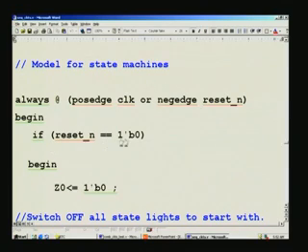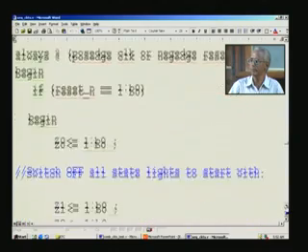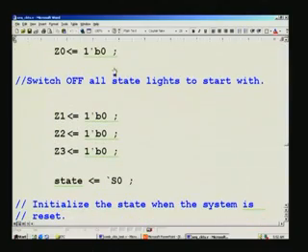So, once again, when reset is encountered, we clear all the outputs here in this case, and initialize to S0 state. Note that I have made it 0, you could have made even 1 as such, because that is what the starting state is, S0 state. But anyway, this will automatically take care, because with the arrival of the next pulse, it will go into S0 state, in which case we would have already covered that.